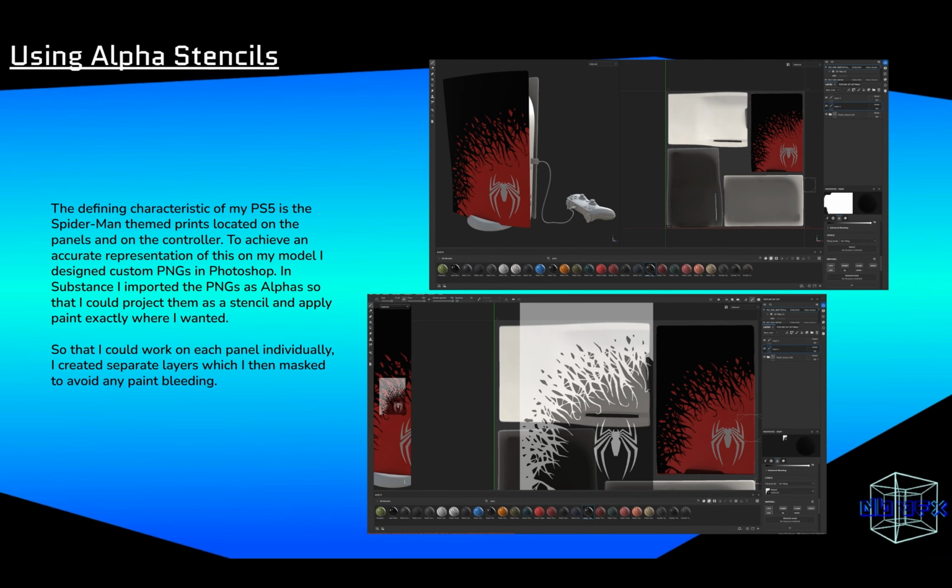The defining characteristic of my PS5 is the Spider-Man themed prints located on the panels and on the controller. To achieve an accurate representation of this on my model, I designed custom PNGs in Photoshop. In Substance, I imported the PNGs as alphas so that I could project them as a stencil and apply paint exactly where I wanted. So that I could work on each panel individually, I created separate layers which I then masked to avoid any paint bleeding.